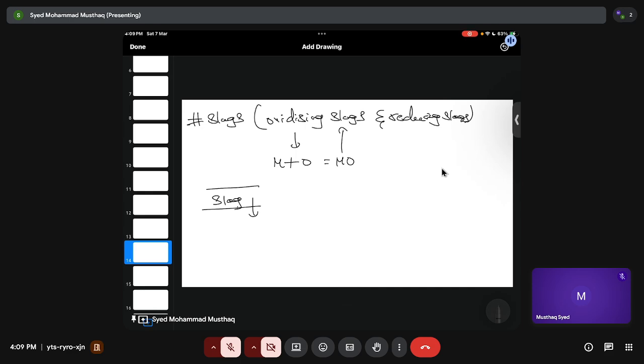So what happens then, let's write an equation. So this is my equation, Fe plus. These symbols are very much important in metallurgy because this symbol represents that it is in slag. The square brackets represent that it is in the metal pool or liquid metal. It is also in metallic state, but this is in slag state. It is ionic form, it will be free ions depending upon the type of slag.